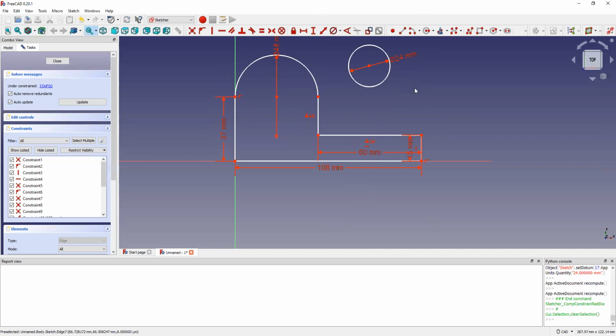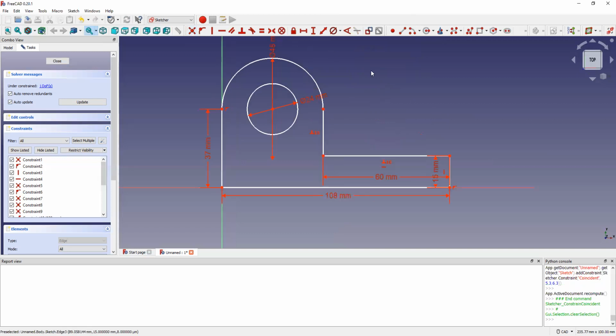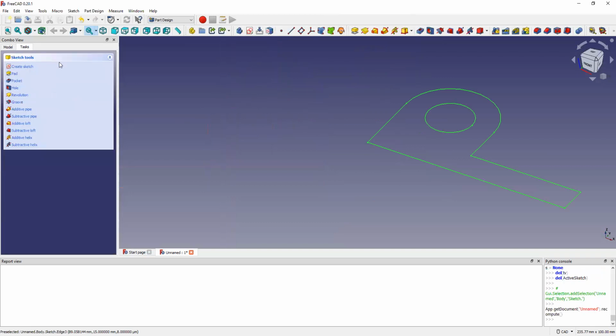You can still constrain it size-wise outside, but after that is when you can now bring it to the center. So the same principle. If you want to ensure that two centers are joined, you click the first point and the next point until all of them turn green. Then you constrain to the center. So what happens after this one? We can run it. So you first of all update, then you close. That's our object.